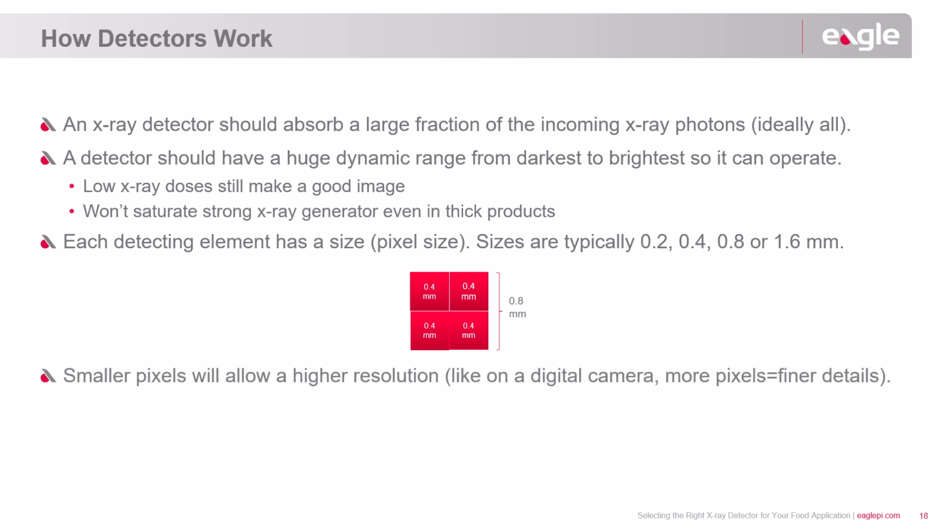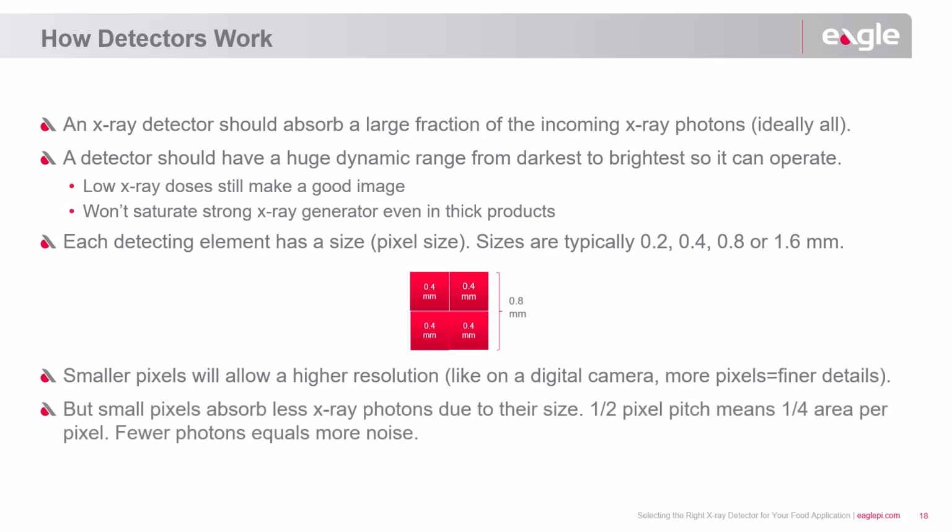With a smaller pixel size, you achieve extremely high resolution and exceptional image detail. This often requires more energy or slower product movement to ensure adequate photon capture. Otherwise, the image quality might suffer due to increased noise. Thus, the choice of resolution and technology should always be guided by the specific application requirements, ensuring that the chosen setup meets the desired specification without unnecessarily compromising on image quality or operational efficiency.